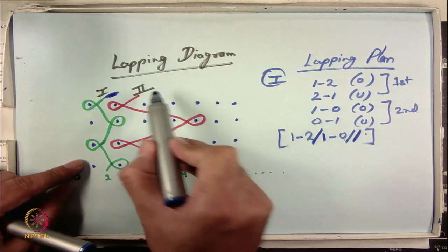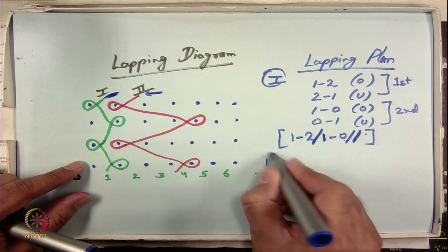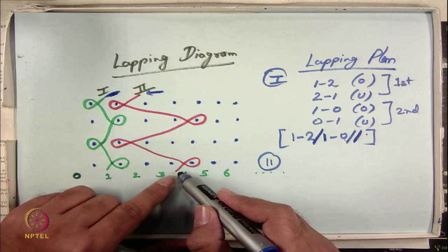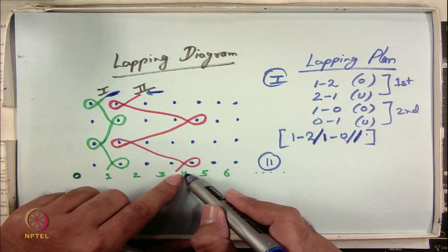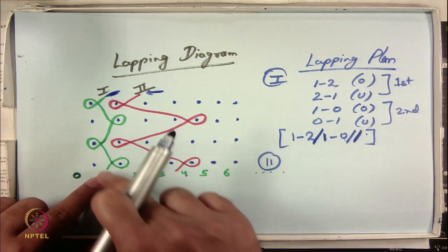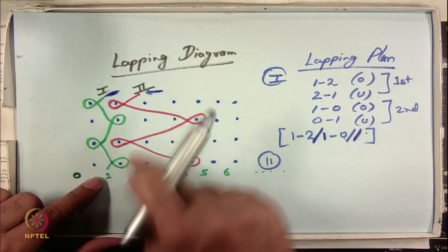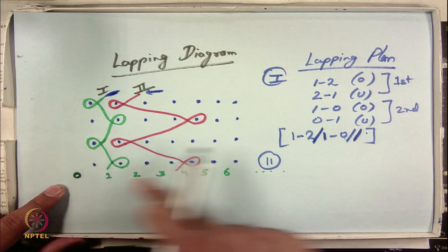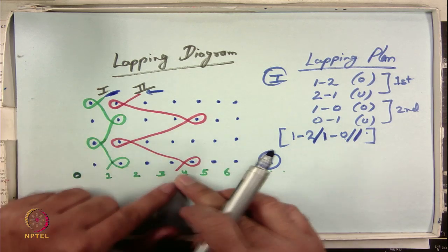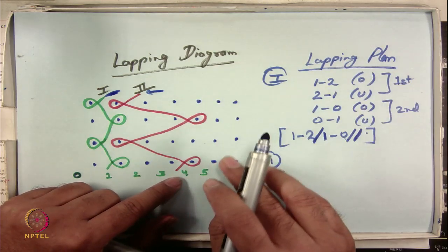Okay. Now, let us see the second guide bar. For the second guide bar we have chosen the lapping position as the fourth position. Please remember, you do not need to only start from the fourth position, you can start from the first position also, and you can follow the lapping plan. But since we have taken the positive numbers, we cannot go to -1 or -2. That is why it is better to start with a position where all the numbers look positive.